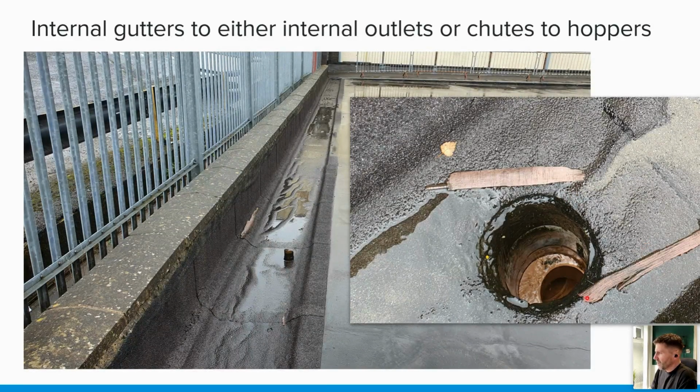Like I say, it's always worth checking these. If there's outlet covers on there, it's always worth taking them off if you can, and just checking the waterproofing around the downpipes.